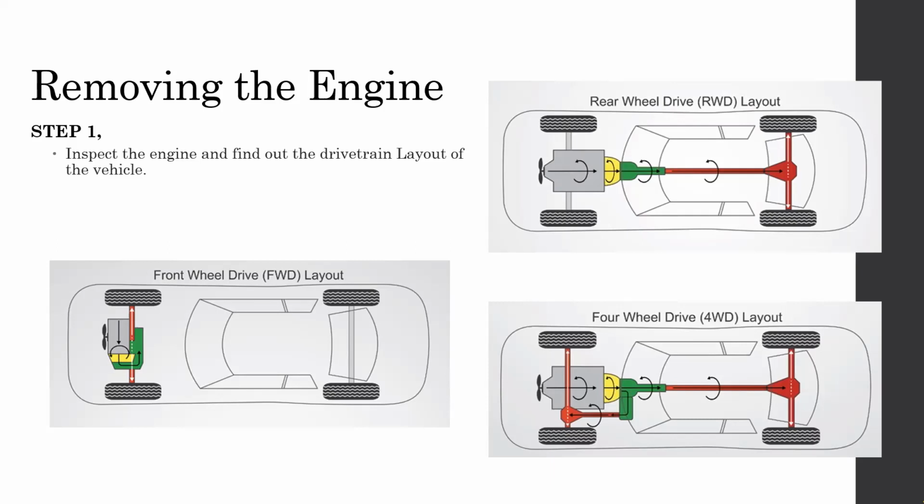There are two fuel systems available for any vehicle. That means it's either a carbureted vehicle, or an electronic fuel injection vehicle, or a manual fuel injected vehicle. Whatever it is, there are two types of fuel systems available. One is the non-return type fuel system, the other one is the return type fuel system. That means the fuel coming from the fuel tank, for example, if we take the carburetor, assume that the fuel pump is located inside the engine bay, then fuel will be coming up to the fuel pump, and it will be delivered up to the carburetor, right?